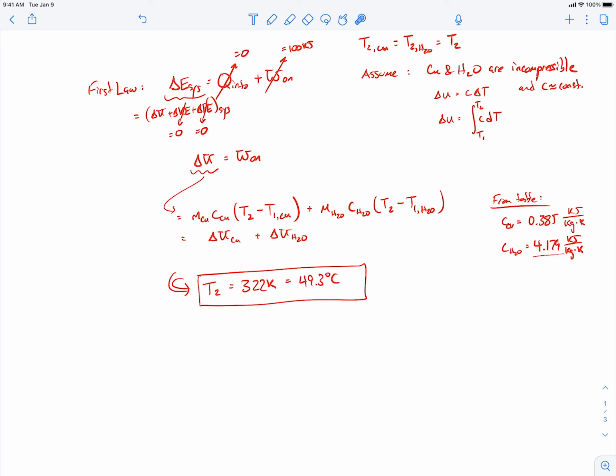But it's fine if you want to use Kelvin instead. That works too. And when you multiply by the specific heat, there's a Kelvin in the denominator of the units. Again, it's the specific heat multiplied by a temperature difference, so the temperature difference can either be in degrees Celsius or Kelvin. It doesn't matter. They're the same magnitude.